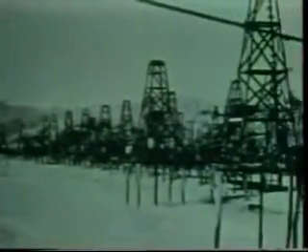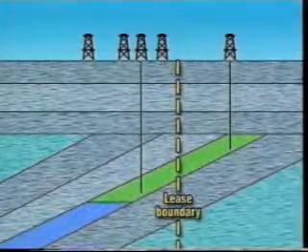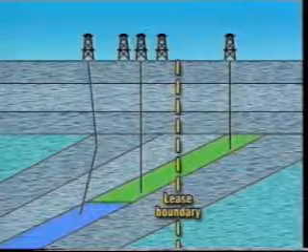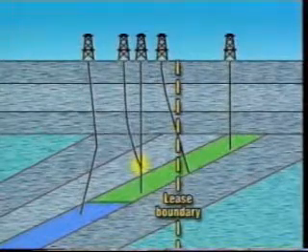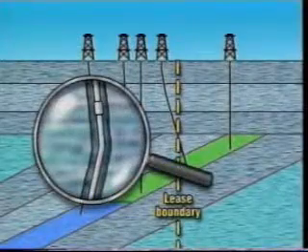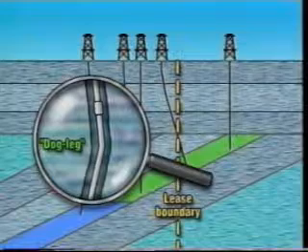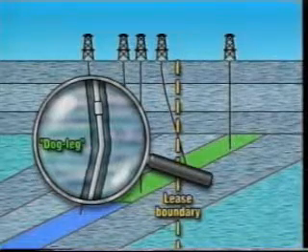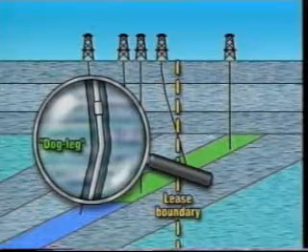It wasn't long after rotary rigs first came into widespread use that drillers developed the maxim, there's no such thing as a straight hole. Wells that were supposed to be vertical often drifted off course, missing pay zones, crossing lease boundaries, or even intersecting other wells. They exhibited abrupt hole angle changes known as doglegs. These resulted in pipe failures and, in extreme cases, made it impossible to run casing or completion equipment.